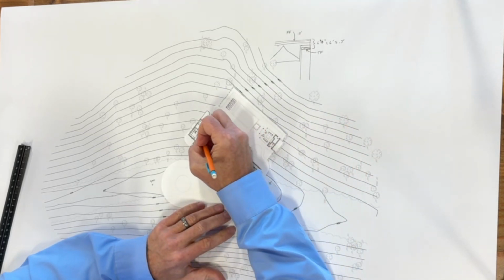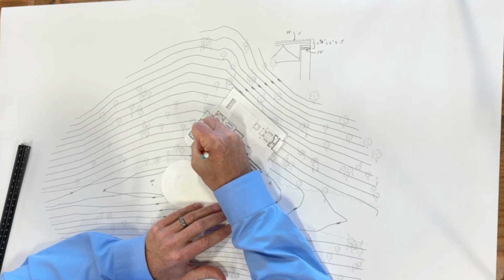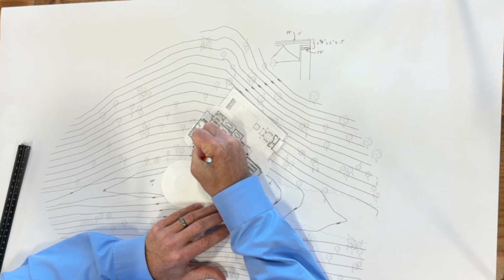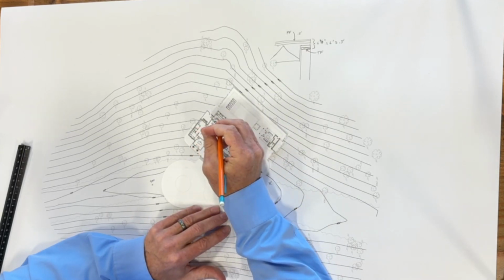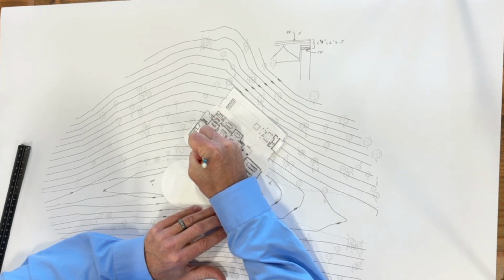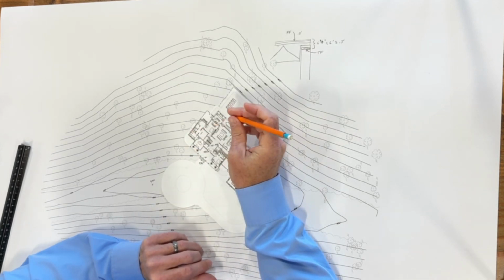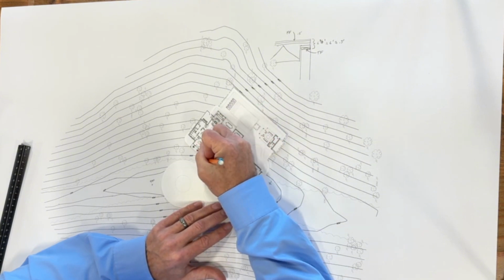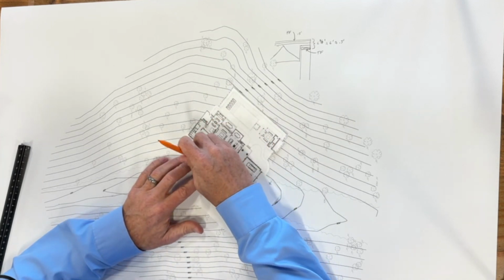So then you start looking at the front door of the home, right? And usually you would have a step down there. So that's a 941.5. And then maybe a 6-inch fall all the way to the front. So that's a 941. And then basically you're going to have, we've got 3 steps shown here. So that'll be at the bottom here, 941, a 939.5. And so, let's see, 941. Yeah, okay. And we may not even need to have that, because we could probably just have a few steps down.